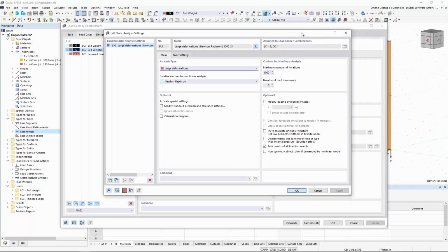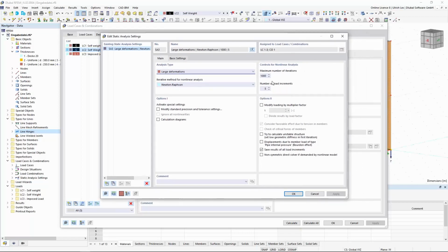For the nonlinear material, it's also necessary to use a number of load increments, so that you don't compute it with only one load increment. It's because the material or the FE element has the chance to be loaded in a slow way.